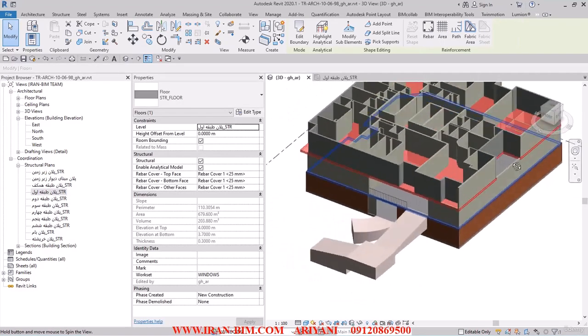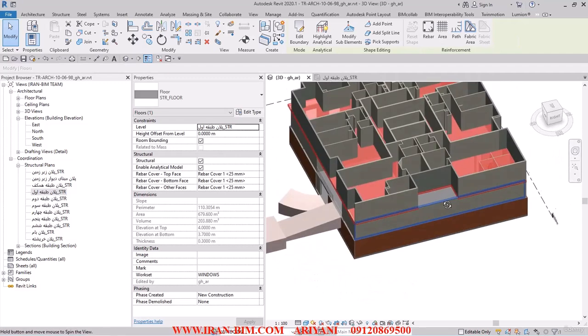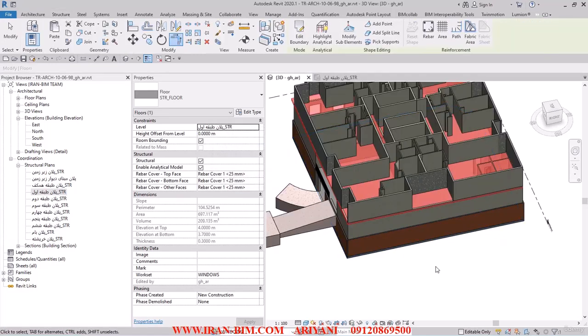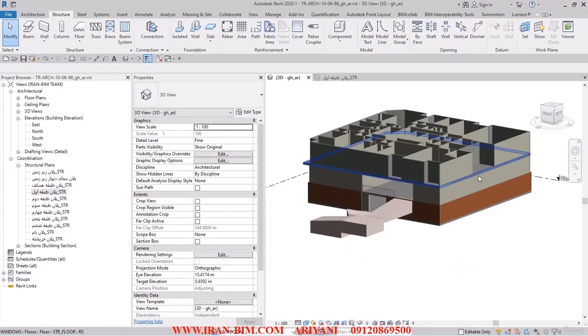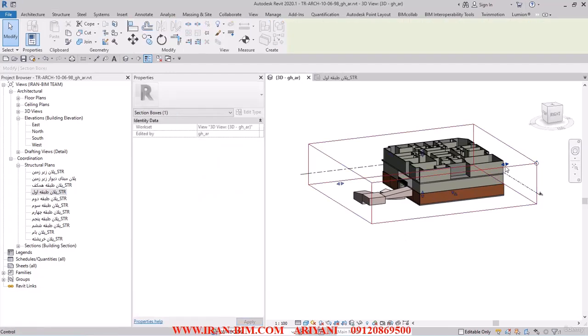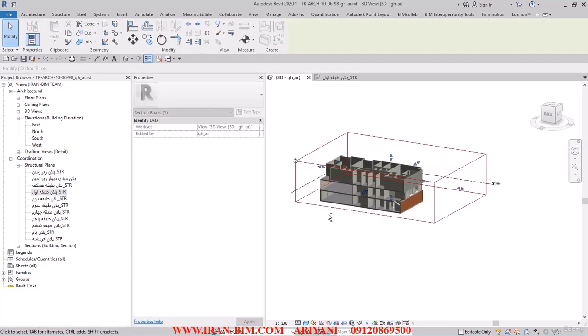So because of that, I think I'm going to have to pull this floor right to this direction. So I select the edit tool, then I'll delete this one, and then this one, and then trim this one, and then don't attach again. So I check the section box to see if there's anything excess and unnecessary, and there we go.